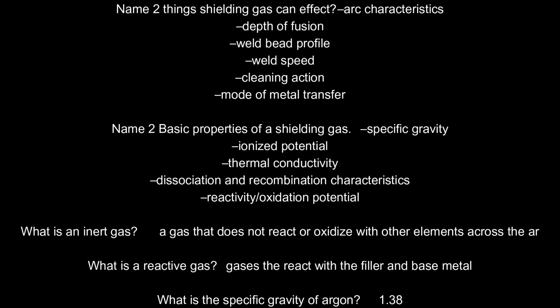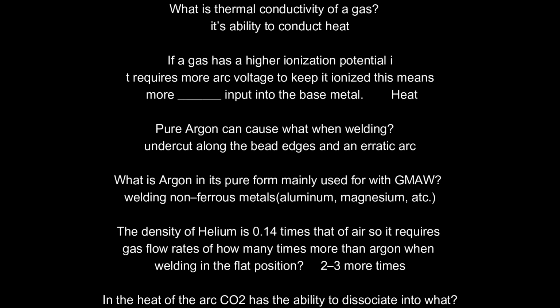What is the specific gravity of argon? 1.38. What is thermal conductivity of a gas? Its ability to conduct heat. If a gas has a higher ionization potential, it requires more arc voltage to keep it ionized.